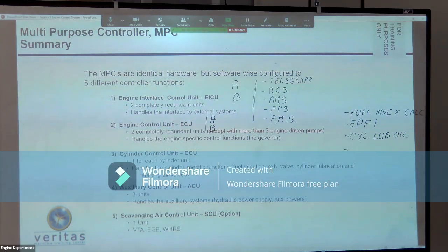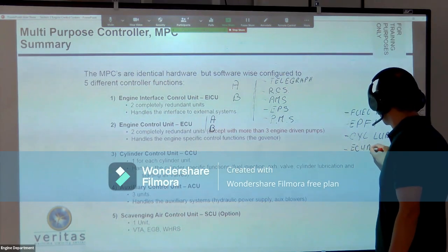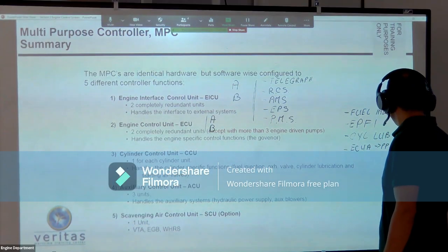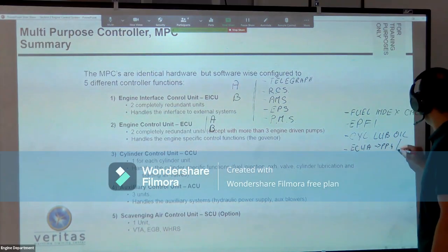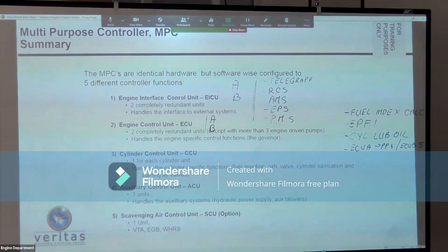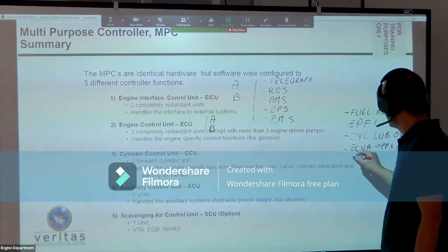So in case you have a large size engine, ECU A is controlling mechanical pump number 4, ECU B pump 5. If we have a large size engine, 200 bar system, they are controlling the source plate position, the flow of pump number 4 and number 5, and are controlling the pilot valve of the main starting valve.